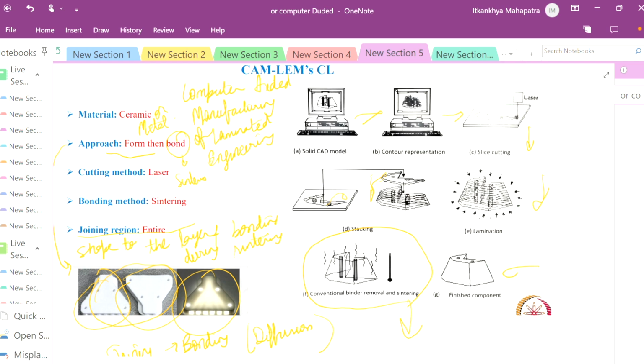So nowadays we are getting metal filament wires, which we can use in various processes, so that we can give a shape to the final product like this, by using a printer. But we have to sinter it. The only problem is that during sintering, the dimensions will change. So we have to take a tolerance of 1 or 1.2, so that there won't be shrinkage. And again, if the geometry is too complex, it is not possible to fabricate with this type of process.